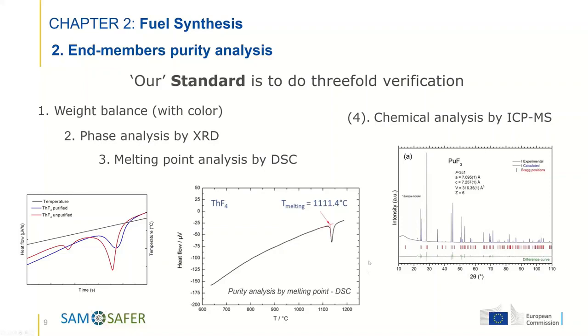Now for comparison, you see the last graph I show on this slide on the very left. You see again thorium fluoride. The blue curve is again a single peak. I don't have the temperature or the time, it's not that important, but this indicates again the same high purity as the middle picture shows. But then we also had not-as-pure thorium fluoride, which still required a conversion of residual oxygen. You could see that there are some pre-melting or eutectics formed, very likely between thorium fluoride and thorium oxyfluoride, and that causes the pre-melting peak. That's an indication that there is something wrong, and we need to purify. So those are the three main steps.